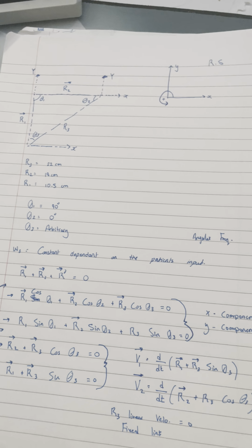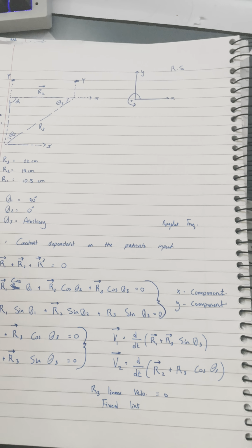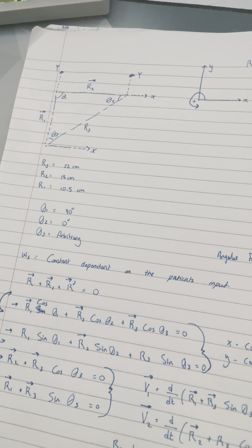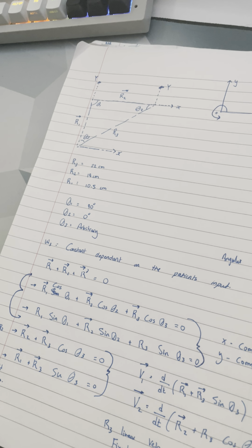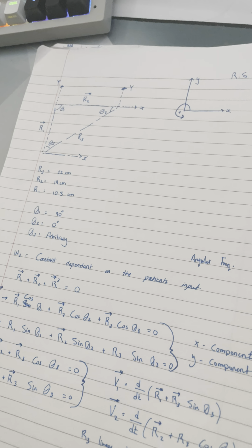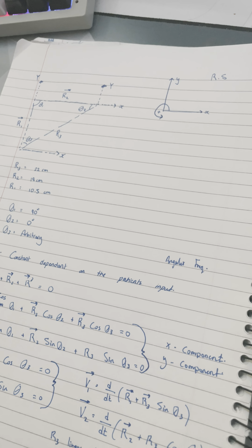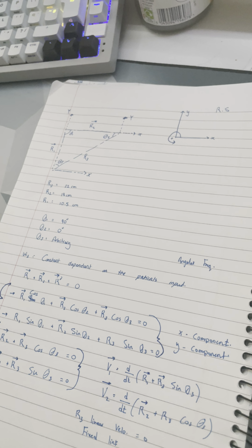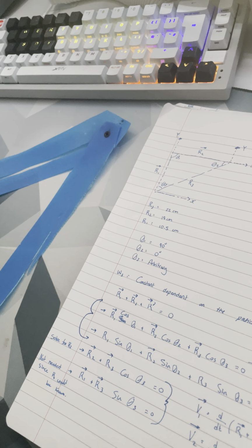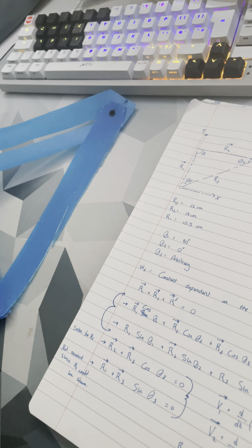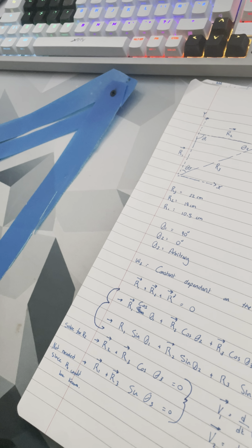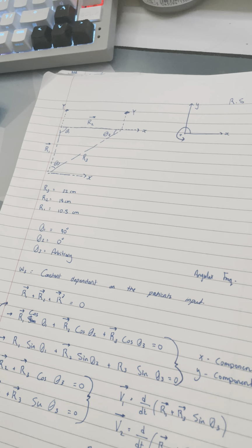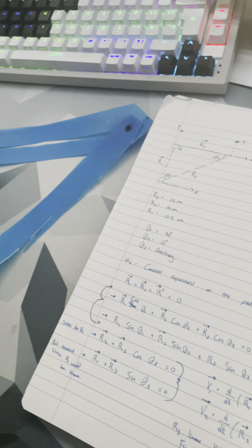I'm going to talk about the mathematical part later, but why is it important? The mathematical analysis is crucial to ensure a natural and safe movement for the patient. The lengths of the fixed links and forearm link, as well as the positions of the rotating joints, need to be calculated in order to achieve a desired range of motion.